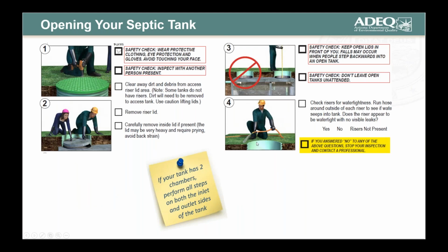So let's review some procedures associated with opening your septic tank. And of course, on our checklist here, we've got our safety equipment. We've got another person here with us, so we're not doing this alone. We're going to clear away dirt and debris from the access riser lid.